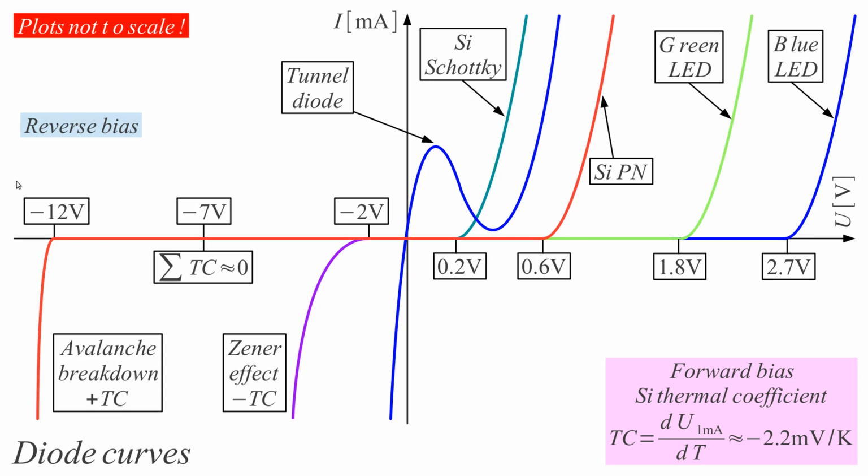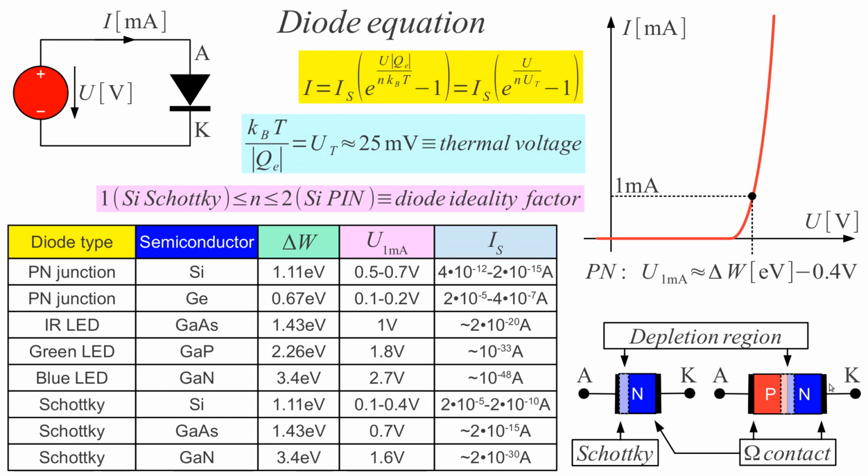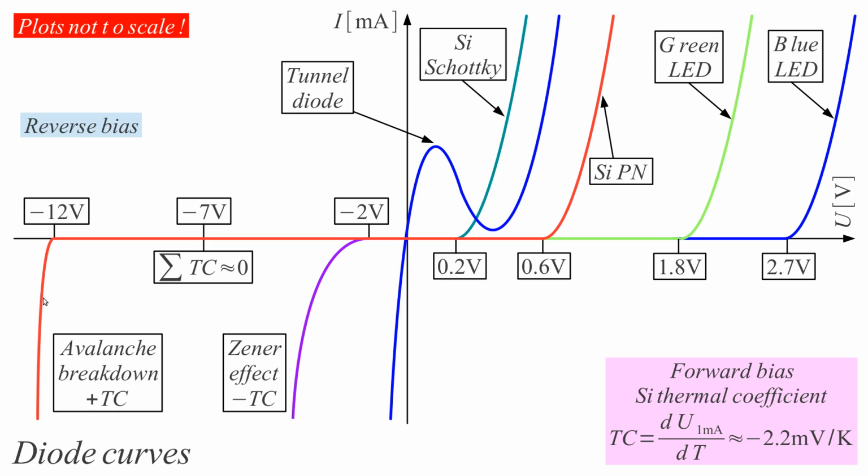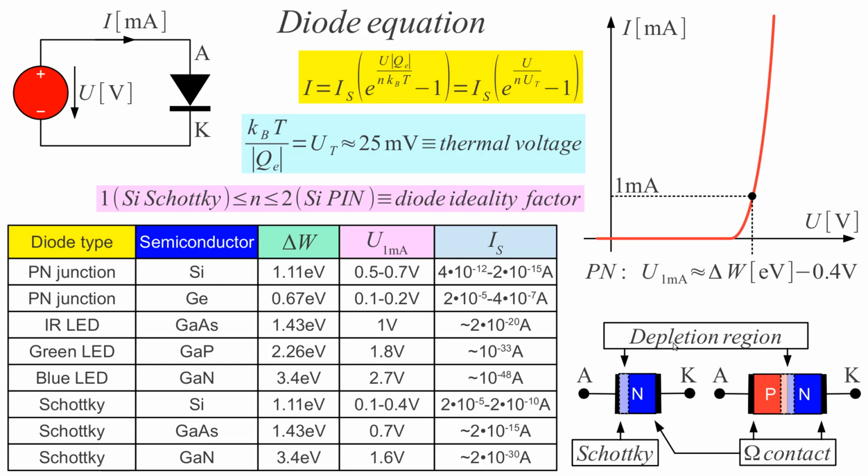Of course, talking about reverse bias, there is certainly a voltage at which our rectifying junction is going to break down, no matter whether it is a Schottky junction or a PN junction. These breakdowns differ according to the amount of doping of impurities in our semiconductors. In order to see a large breakdown voltage, we have to have very light doping, very clean semiconductors.